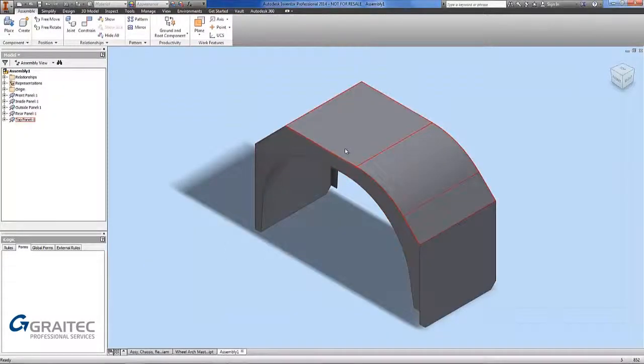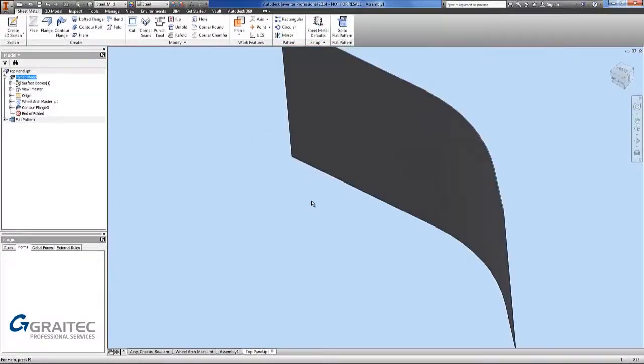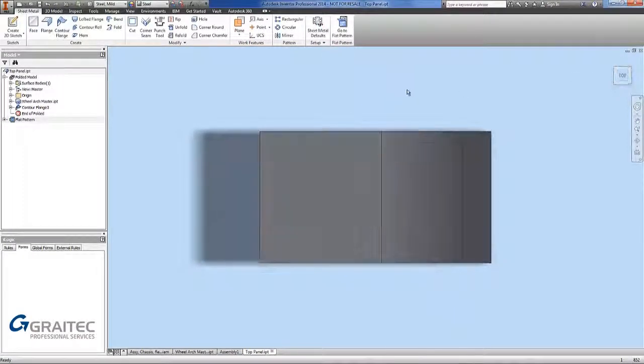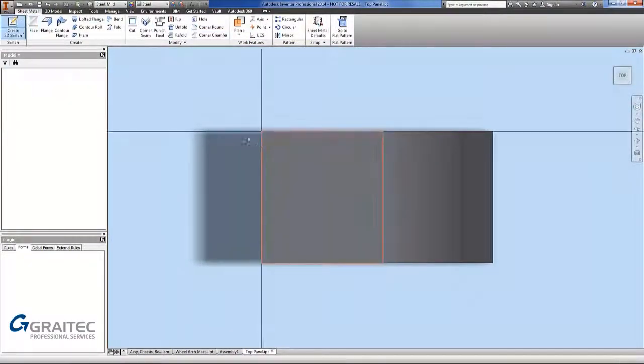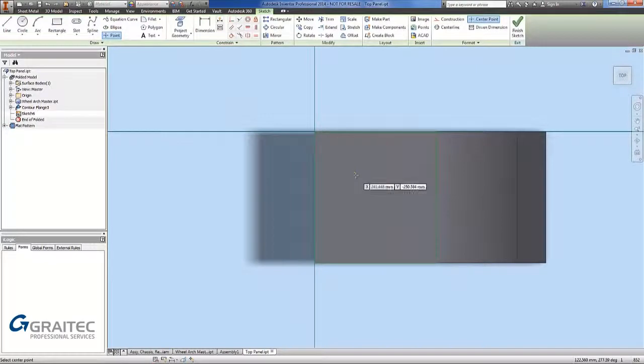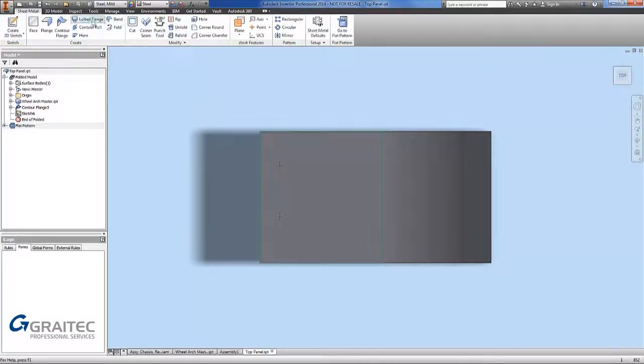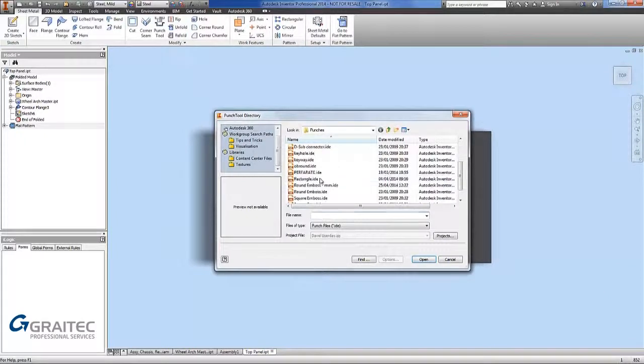We can use the sheet metal punch tool to create nice features on the surface. However, it doesn't always give you the naming that you want. As an example, we're just going to put a punch on here quickly. Normally I would constrain these points in place, but for this example it doesn't matter too much. Find our punch, we're going to find one called perforate.